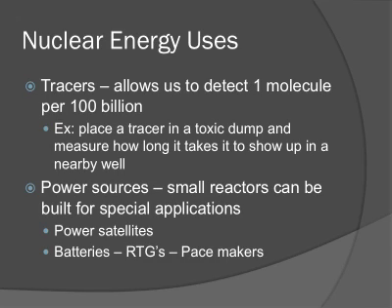One example of why we would use this is if we have a waste site. It doesn't necessarily have to be a nuclear waste site, it could just be a landfill. We want to know how fast the contamination is going to spread in our groundwater, right? Because we don't want the pollution from landfills getting into our water, correct? So how fast would this happen? What they could do is put a radioactive tracer at the landfill and then find a well nearby and continually check the well for that tracer.